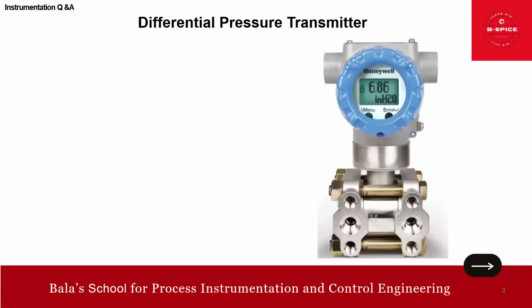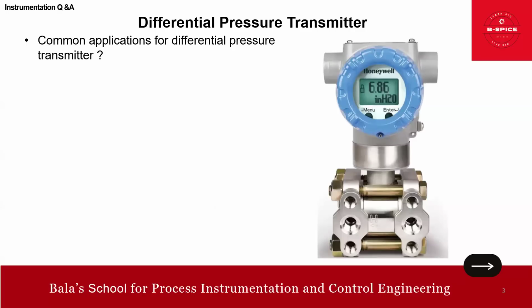So now let us move into the specific interview questions related to differential pressure. What are the common applications of differential pressure? Differential pressure is used in a variety of applications, including flow measurement in pipes, by creating a pressure drop with an orifice plate, venturi tube, and so on.